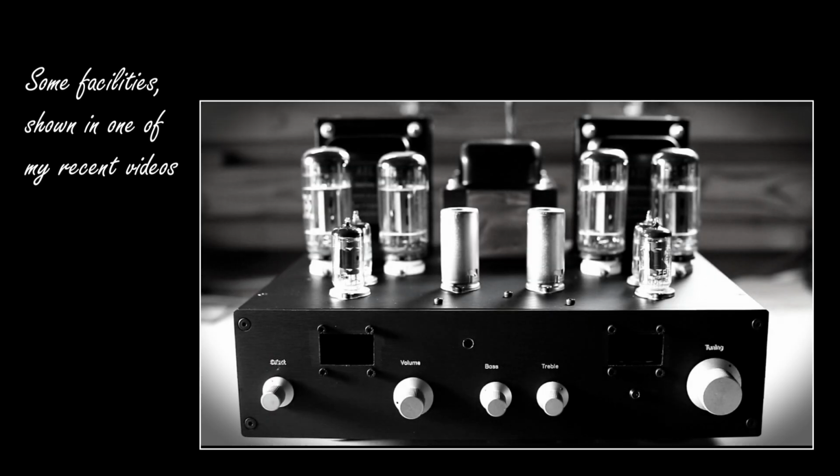Let's wake up fully the amplifier now through the remote control. As you can see, the Arduino, the microcontroller, is performing some initial checks before giving green light to the amplifier. In this moment, the microcontroller was measuring the current flowing through each one of the power tubes, and only when the current gets higher than a certain amount, the microcontroller gives a green light to the amplifier. So in this moment, this was achieved.